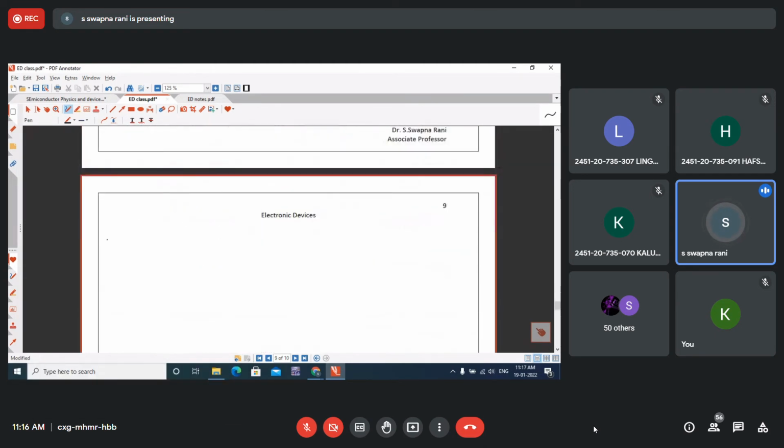Now I will repeat the same thing. Channel is said to be pinched off at VDS sat, which is equal to 4 volts, or put another way, channel is said to be pinched off when VGS equal to -4 volts. I'm giving you these numericals just for easy understanding.